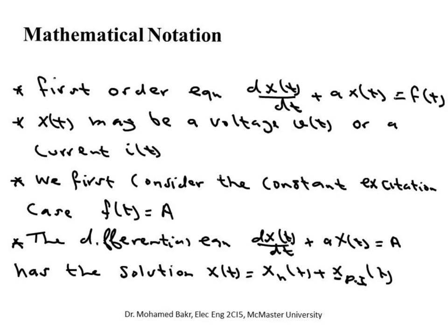We'll start by discussing first the template, and then I will show you how to apply this template to many circuits. We are giving here a differential equation in the form dx(t)/dt plus a x(t) equal to f(t). x(t) can be a current or a voltage, a is a constant, and f(t) is our excitation. We are going to limit ourselves a little further to the case where f(t) is a constant, capital A.